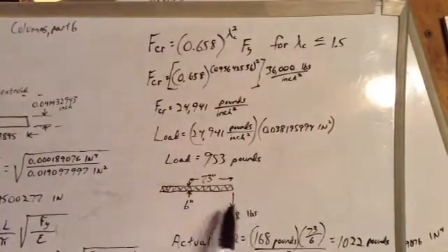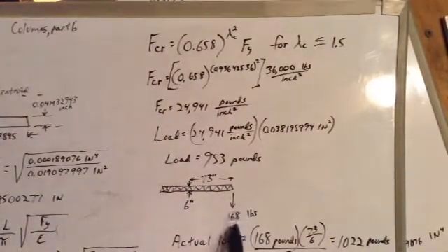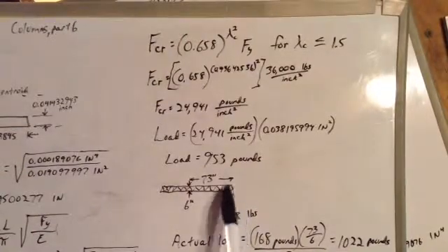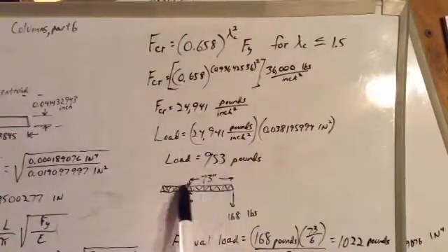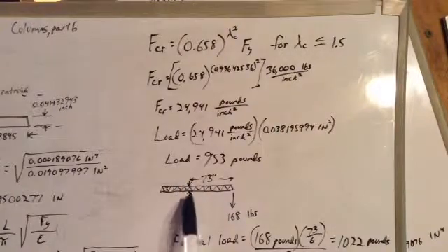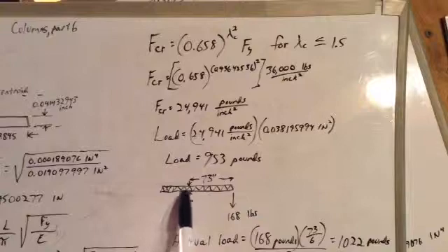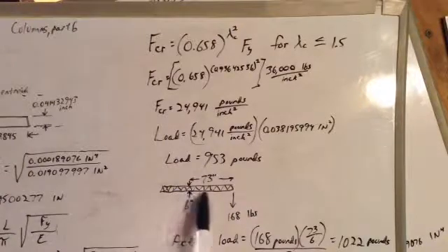This mock-up tail boom of the Steel Stork was loaded to 168 pounds before it finally collapsed, and that was about 73 inches away from where it collapsed. And the top flange was 6 inches above the bottom flanges, two bottom flanges. It was triangular.